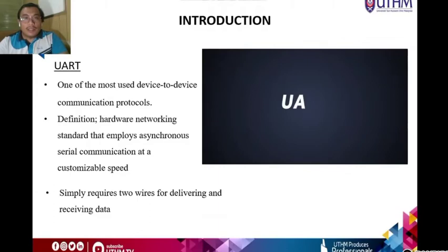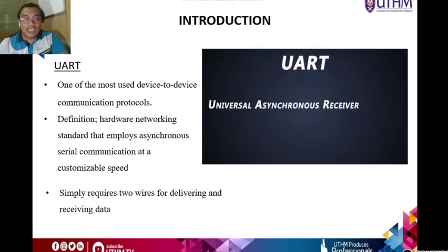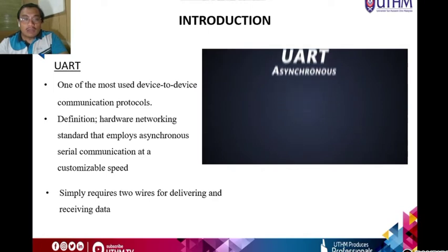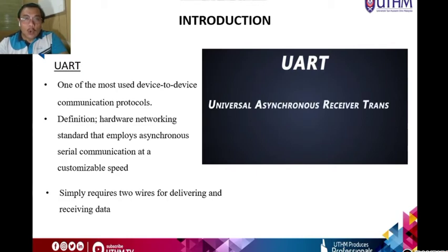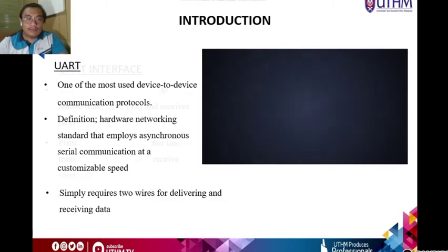For introduction, UART or Universal Asynchronous Receiver Transmitter is one of the most used device-to-device communication protocols. By definition, UART is a hardware networking standard that employs asynchronous serial communication at a customizable speed. UART is one of the few communication technologies that simply require two wires for delivering and receiving data. When utilizing the UART module inside the microcontroller, proper frame protocol implementation is sometimes discarded.